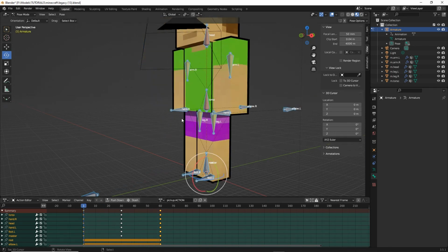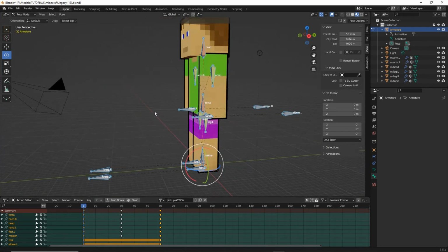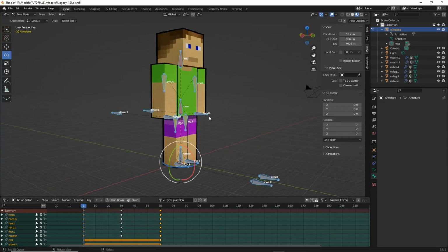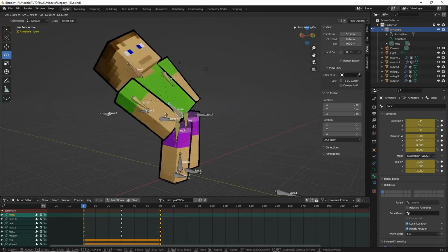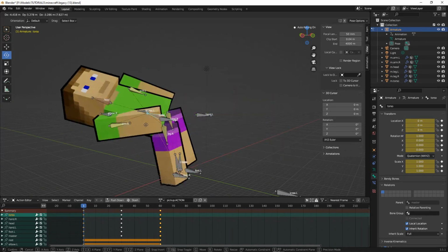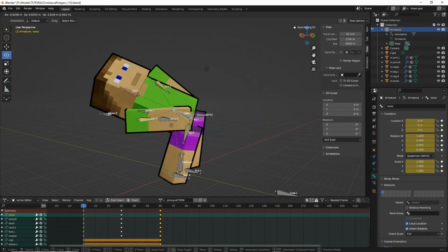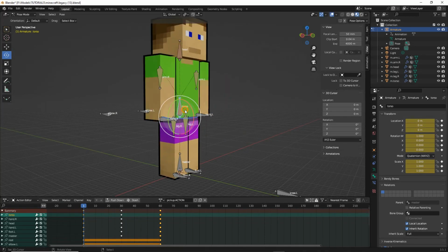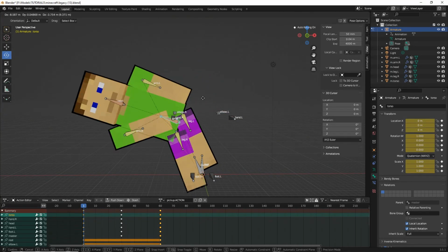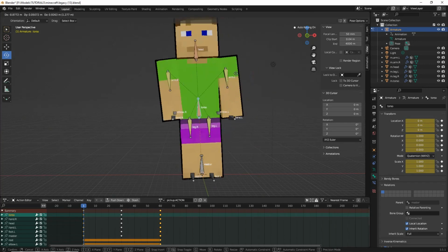And that just tested our rig setup, because as we saw, we needed the torso bone to move independently of the root bone, but we still needed the IK so that we get the effect of being able to manipulate all the bones as a group.